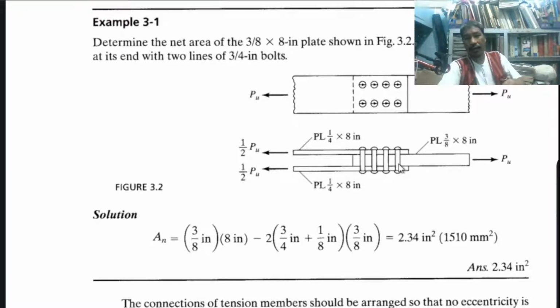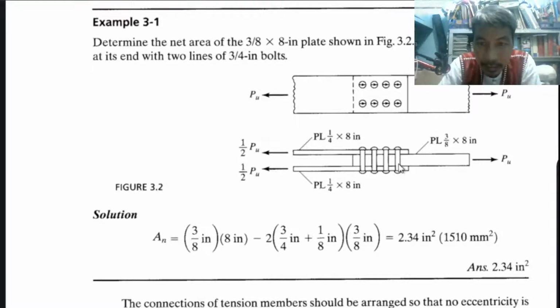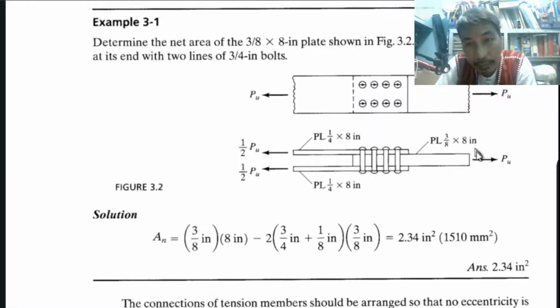So that is the weakest line. This is weakest line number 2, weakest line number 3, and weakest line number 4. You will notice these weakest lines have the same number of holes. There are 2 holes per line. If I draw an arbitrary line here, it is stronger because there are no holes.